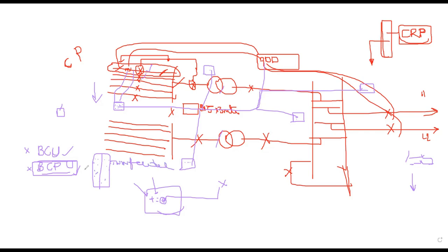Because there is no requirement of additional relays, there is space availability. So the two feeders' control and protection can be accommodated in a single panel with the help of the BCPU. So this is the latest one. All the developers are looking ahead to this twin feeder panel.